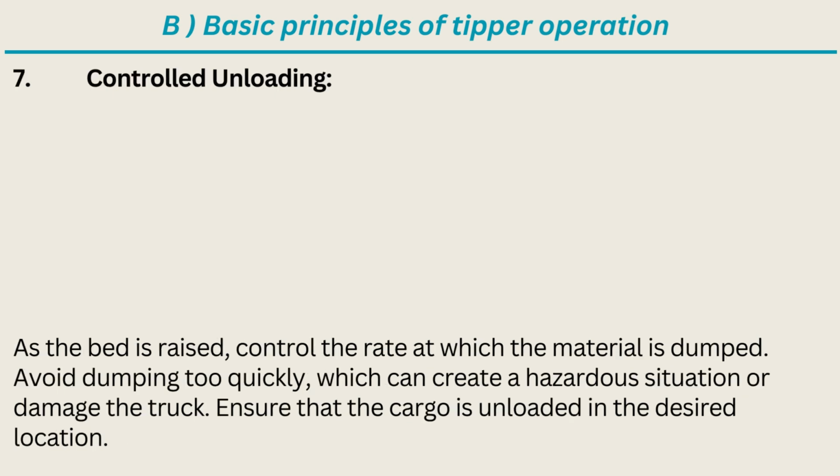7. Controlled unloading. As the bed is raised, control the rate at which the material is dumped. Avoid dumping too quickly, which can create a hazardous situation or damage the truck. Ensure that the cargo is unloaded in the desired location.